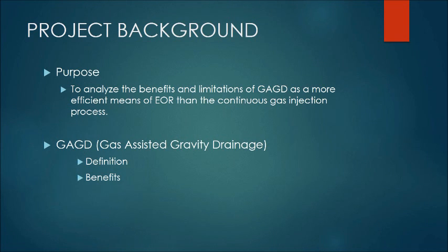Hi, my name is Ricardo Jagpath, and I'll be giving a quick background on our project. The purpose of our project is to analyze the benefits and limitations of GAGD as a more efficient means of enhanced oil recovery than the continuous gas injection process. The principle of CO2 enhanced recovery is the alteration of the physical characteristics of the oil due to interaction with CO2 molecules, which enables greater hydrocarbon recovery and production.